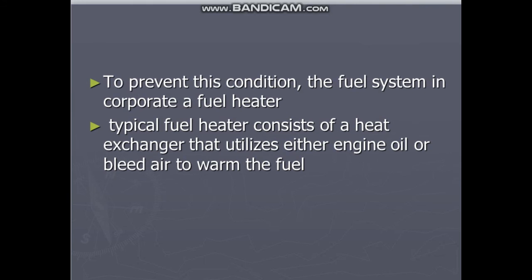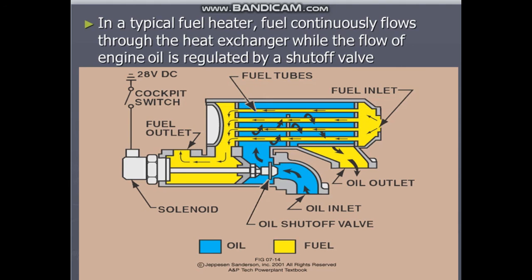To prevent this condition, the fuel system incorporates a fuel heater. A typical fuel heater consists of a heat exchanger that utilizes either engine oil or bleed air to warm the fuel. In a typical fuel heater, fuel continuously flows through the heat exchanger while the flow of the engine oil is regulated by a shut-off valve.